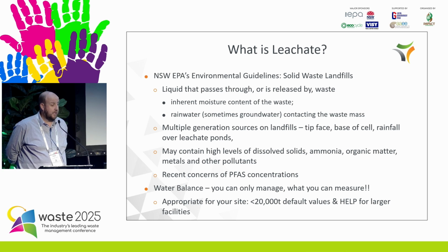Water balance, obviously, make sure you get one done, guys. You can only manage what you can measure. And of course, the New South Wales guidelines give plenty of guidance on how to actually do that. For smaller facilities, less than 20,000 tonnes, there are default values. Beyond that, you've got to be looking at the HELP model, the hydrological evaluation of landfill performance, which is a more detailed analysis of what we think is going to be generated.